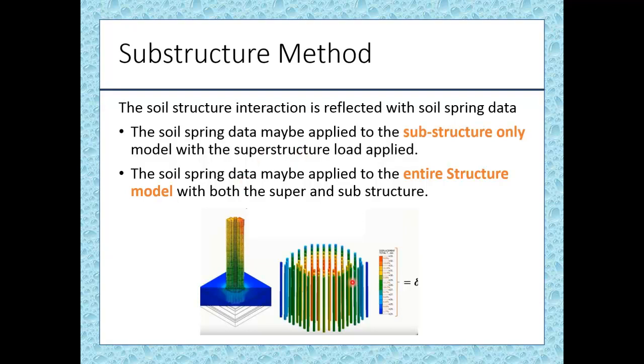The second handles the entire structure together, the substructure and superstructure, and then gets the results. The first, substructure-only approach is commonly used. However, when we have to consider soil structure interaction, it may affect the superstructure as well, so considering only the substructure is not that useful.